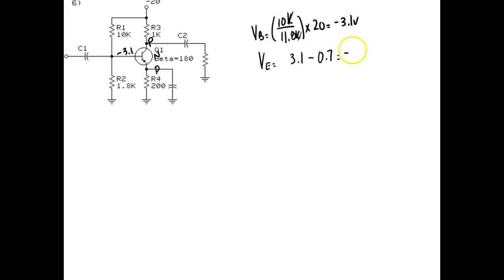2.3? Yes. And then IE, of course, current has no sign. 2.4? Okay, then IE has no sign, so it's going to be 2.4 divided by 200 ohms. What's that? 12 milliamps. I can see that. That's one of those you can do in your head, just about.